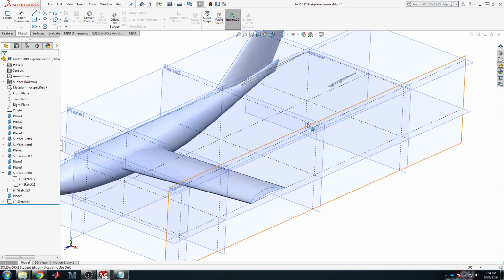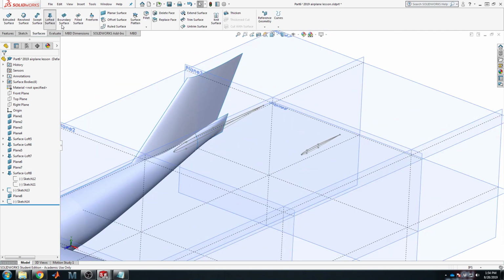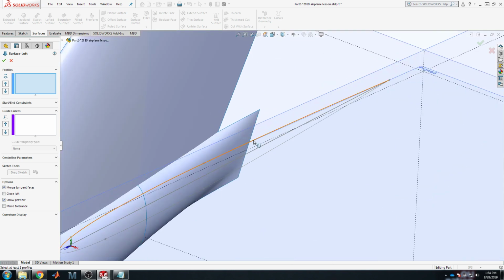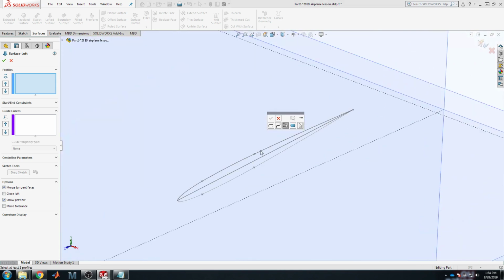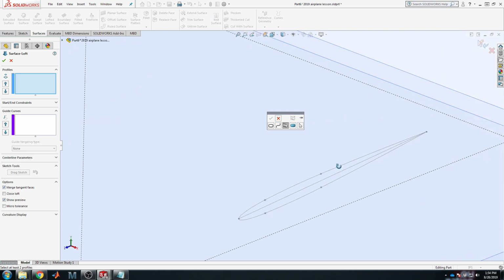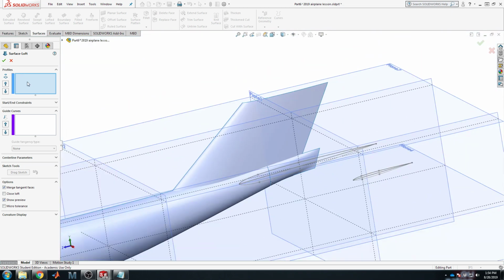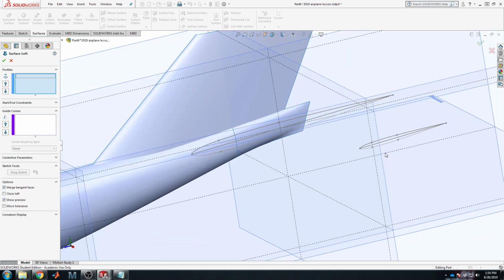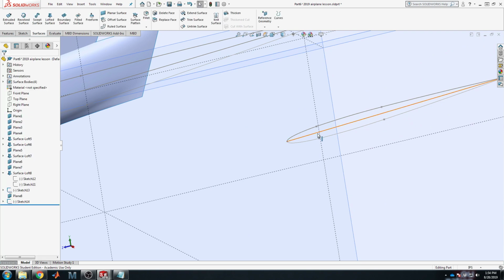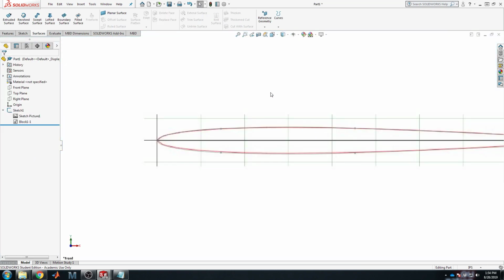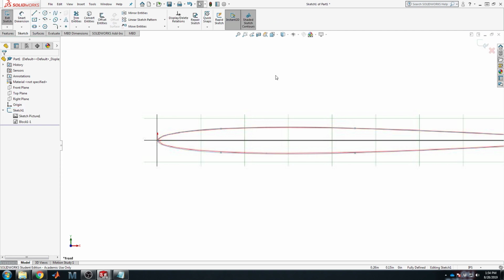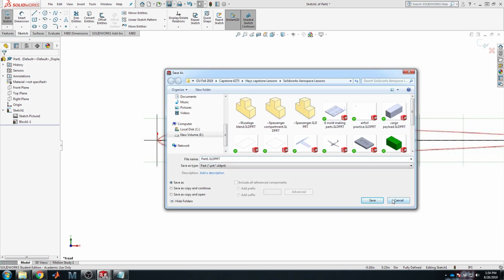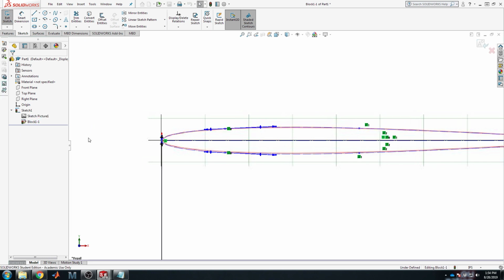And okay. Sketches are placed, leaving only surface, loft, this cross section to this. What? Come on. Apparently it's not selecting the whole path. Oh. I think I might see the problem. Good thing I didn't close that other thing. Let's go back and edit the block. Because I didn't turn that horizontal line into a sketched line. Let's save. Interesting. Guess we need to edit the block.